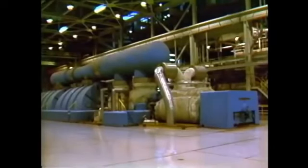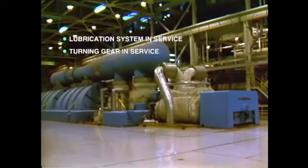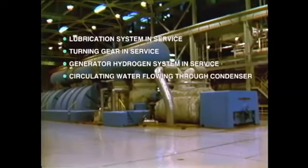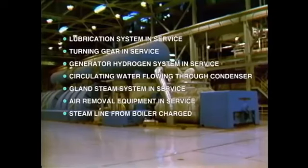Summarizing, then, the following conditions must be established before steam can be admitted to the turbine. Lubrication system in service. Turning gear in service. Generator hydrogen system in service where applicable. Circulating water flowing through the condenser. Gland steam system in service, providing sealing steam. Air removal equipment in service with vacuum established in the condenser. Steam line from the boiler charged and turbine stop valve open to charge the steam chest.